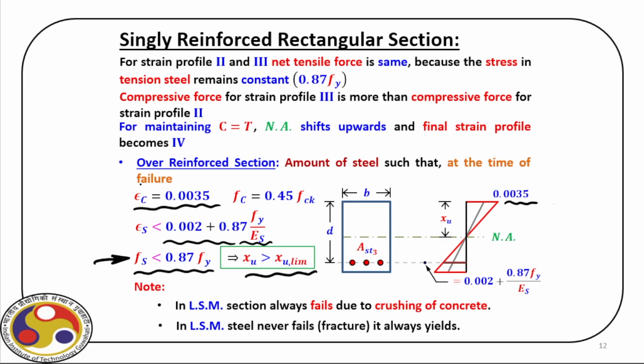Because we still have the amount of strain in steel less than its limiting value, the steel can take some more strain, but the concrete has already reached its limit, and therefore further applying moment at the section level will cause a failure. Okay, and that's why it is a brittle failure and it is not recommended.